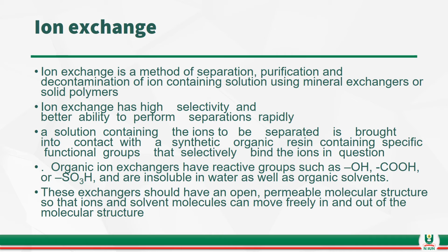Ion exchange technique. Ion exchange is a method of separation, purification, and decontamination of ions containing solution using mineral exchangers or solid polymers. Ion exchange has high selectivity and better ability to perform separations rapidly. A solution containing the ions to be separated is therefore brought into contact with a synthetic organic resin containing specific functional groups that selectively bind the ions in question.